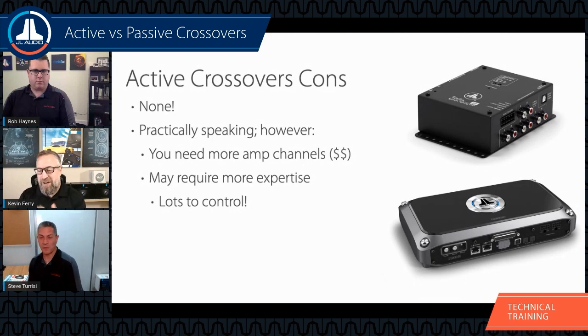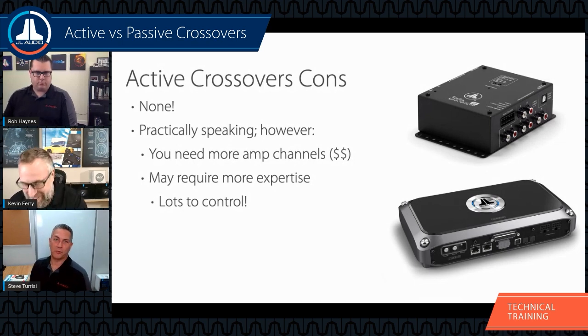You have crossover points of 3 different speakers on there, and it becomes a lot more critical. And honestly, if you're doing a 3-way, active is the absolute only way. It's the passive parts, the components alone for those lower frequencies, they become hideous. The physical size of them to prevent the losses doesn't make sense. Just go active, man, all day.